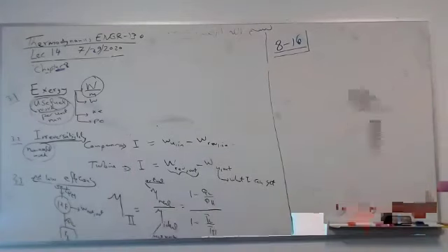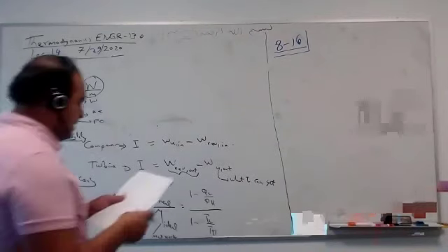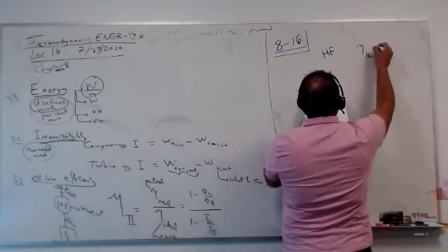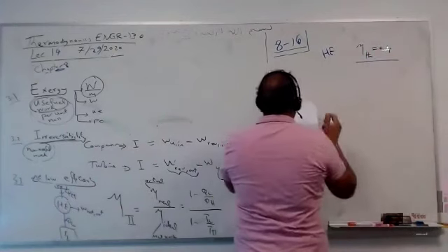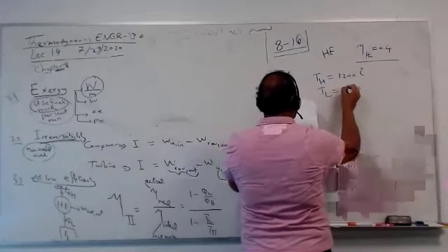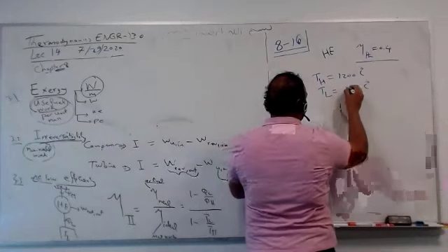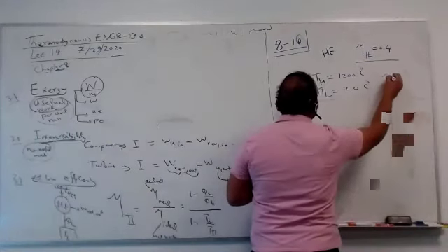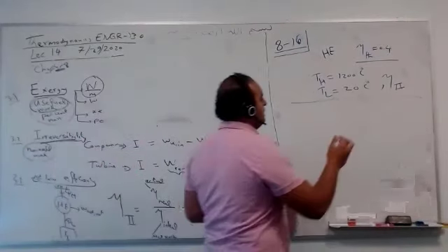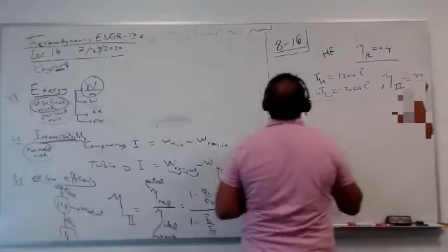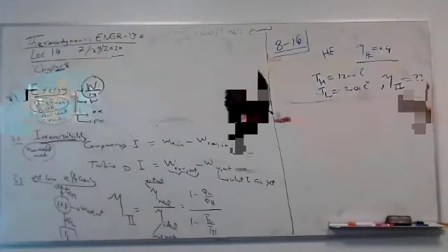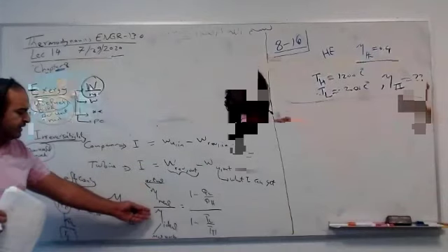So the last problem, guys, please, which is a heat engine with thermal efficiency of 0.4. Yes, that's a typical value. I give you T high was 1200 Celsius and T low, I think 20 Celsius. You find the second law efficiency, eta double I. It's a heat engine. We need the second law efficiency. So it's eta real over eta ideal.